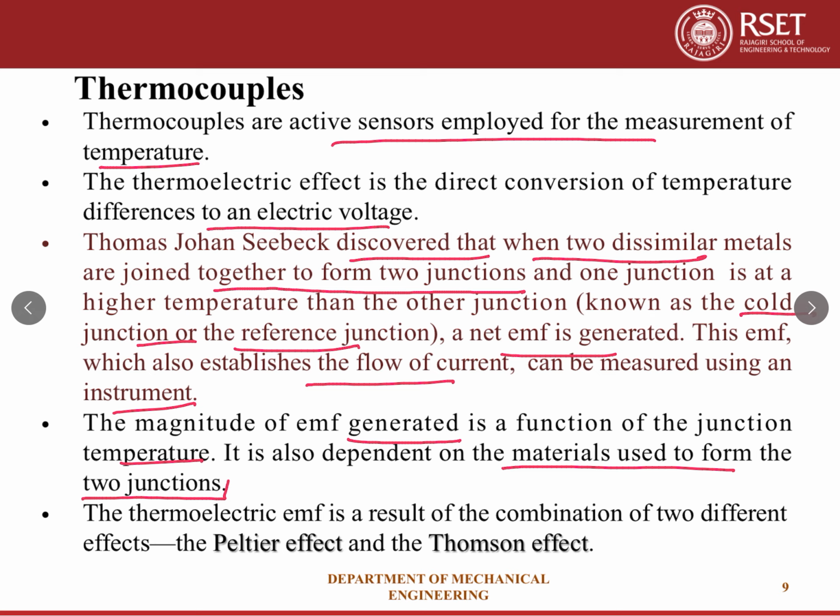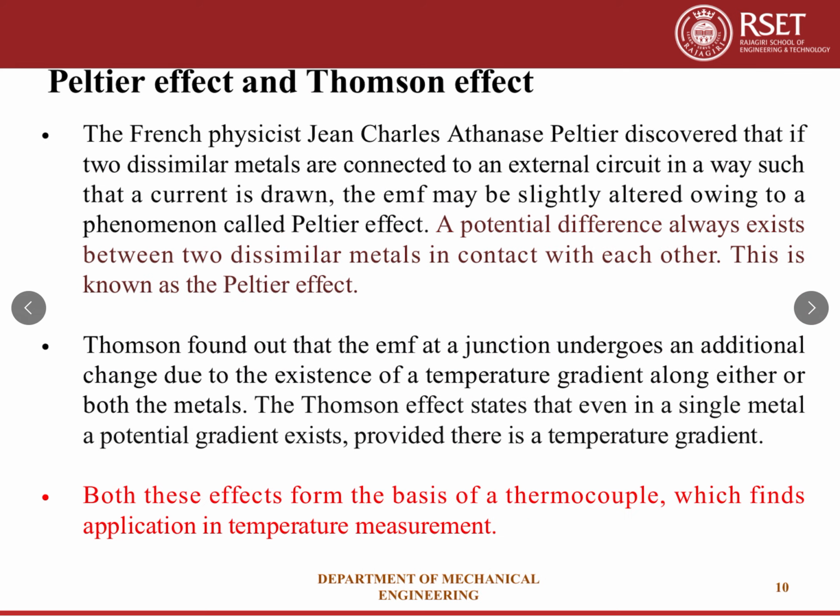So the thermocouple EMF is a result of a combination of two different effects, the Peltier effect and the Thomson effect. We have seen that the EMF generated in the thermocouple is a function of junction temperature and the material used, two factors affecting the EMF generated. Then we have two different effects, the Peltier effect and the Thomson effect, to explain the thermocouple or thermoelectric EMF. We are going to study about the Peltier effect and the Thomson effect.